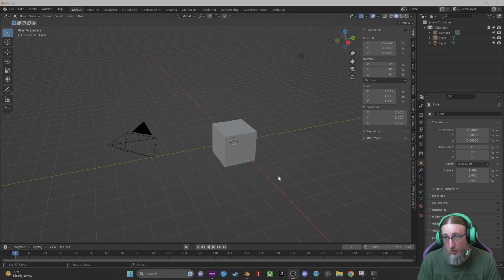So what I know I need to do here is reverse it. And the way to do that is to come over to your modifier tab, the little toolbar there, and go over to where your strength is. And instead of 0.02, I'm going to change that to negative 0.02. And that's just going to reverse the strength on the image so that the white is lower and the darker gets thicker, and the thinner you have is for the white. So I want the lighter colors to go down and the darker colors to pop up.